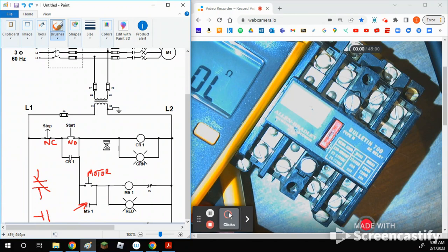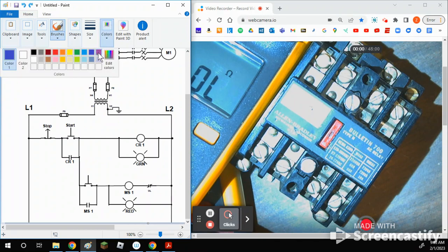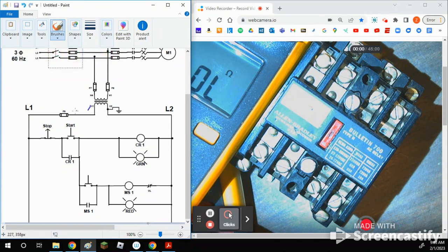You guys confident in your numbering to where you think you could do this by yourself? Yeah? All right, where are all my ones? Going all the way to the stop on the left side. One. That little jumper wire should already be in there for you. One all the way to the stop. Where are all my twos? Everything right side until it hits something. Correct. And what's another name for all the twos? Neutral. The neutrals.